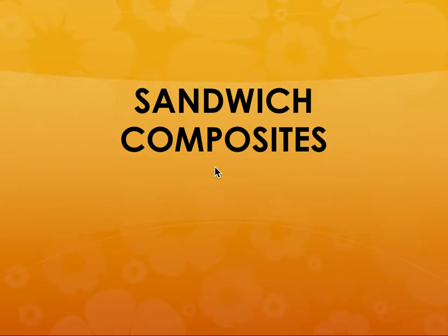Second part of lecture 9, and here we start with talking about what are sandwich composites. Why do we want what are called sandwich composites? Because if you have only the composite by itself, what is the density of a typical polymer matrix composite? Carbon is about 1.8 to 1.9 grams per cc. Most resin matrices are approximately of the order of 1 to 1.1 grams per cc.